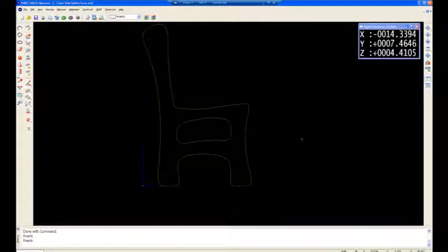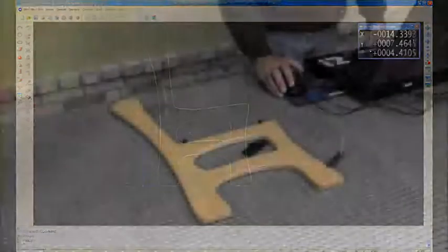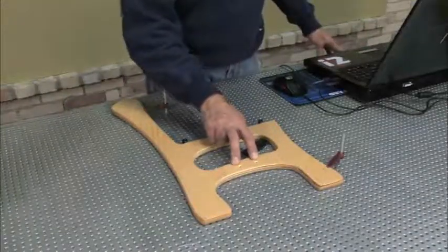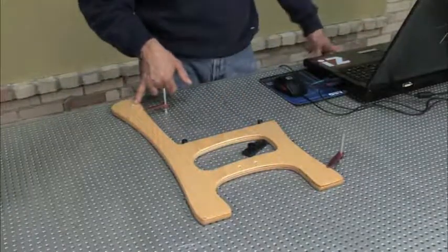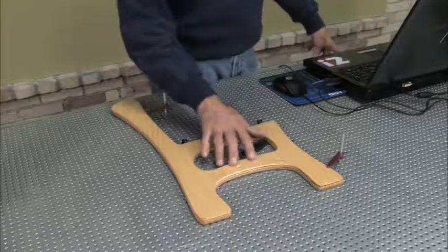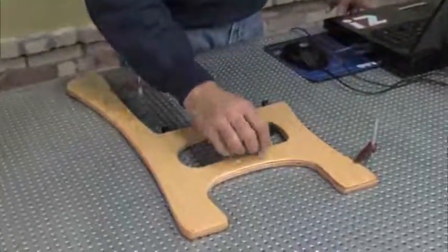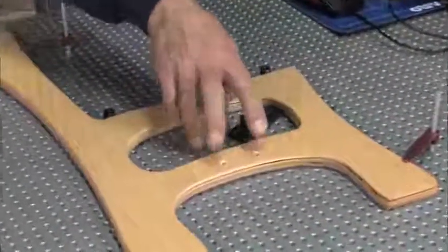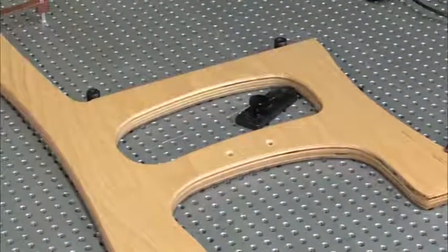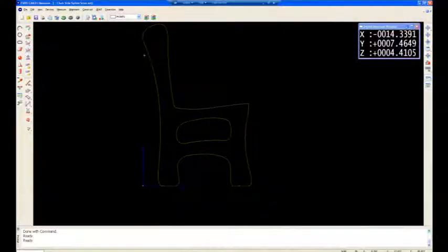Now you'll see in my SAT file I've tracked the perimeter geometry with a 2D freehand scan. But what I have to do is find the location of these 2 points here and this point up here as well. And my client's fine with that just being a single point. He can find out what size that is with some calipers or a gauge pin, but we need the center point tracked in there. And the way I'm going to do that is with a planar point.